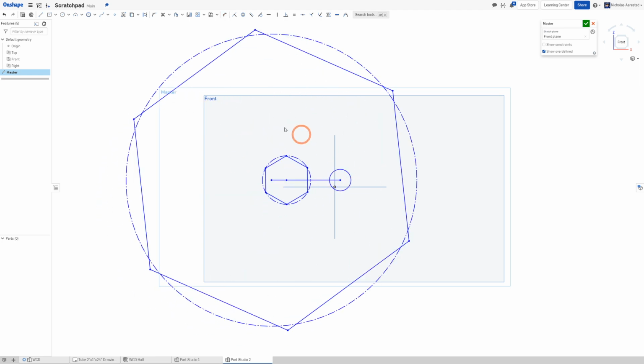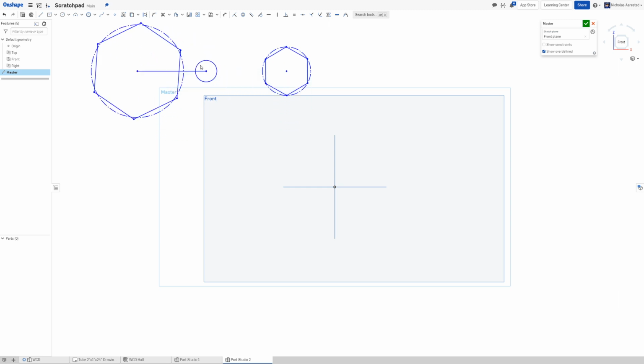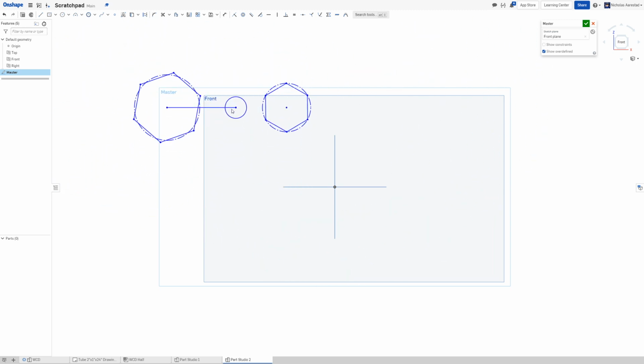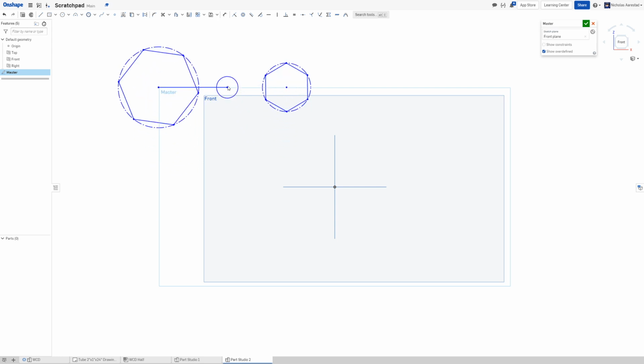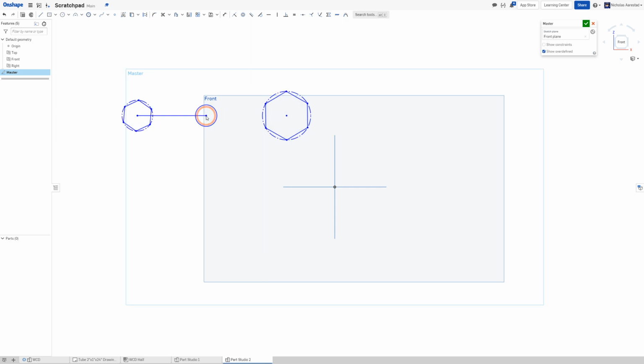And then I can drag these all around, and since everything's blue, everything's screwed up when I drag things around because I didn't constrain things. So this is kind of the second key point of this video: if you see blue, you either made a mistake or you're not done yet, right?